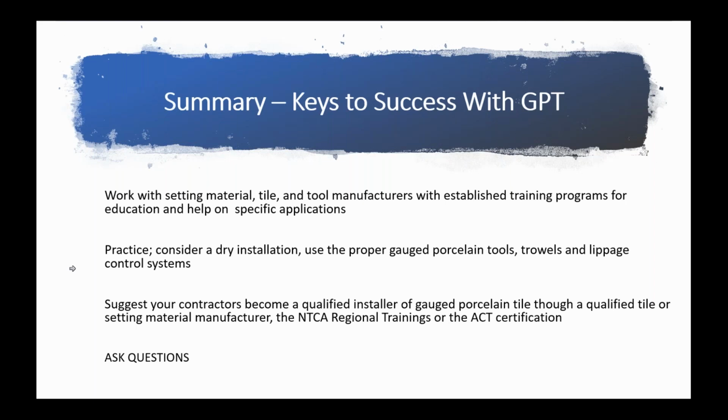it in fairly square. But who's got the top, who's got the bottom, who's going to do the beading in, who's going to do the troweling, et cetera, have it all planned out. Definitely to your advantage. It's the only way you're going to become efficient at it as well. Use the proper gauge porcelain tile tools, trowels, and lippage control systems.